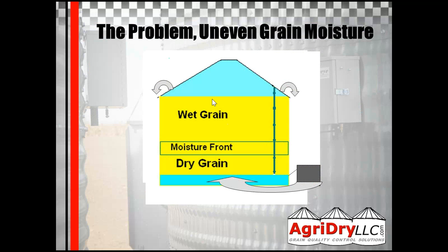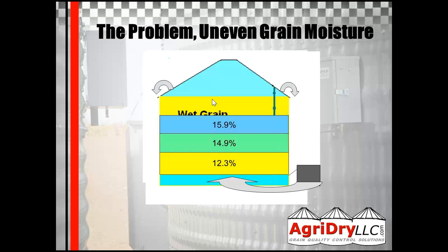So we've talked a lot about what your bin should be set up for when it comes to horsepower, roof vents, calculating CFM per bushel, and what your expectations are for your equipment. And then when we put our equipment on the bin, we make it more efficient. So typically, I hear a lot of producers tell us they're running their fans 24 hours a day, let's say for 2 months straight, and by 2 months in, before they go into the winter conditions, they say, well, my grain moisture should be dried and my temperature should be cooled down and ready to go into winter storage.